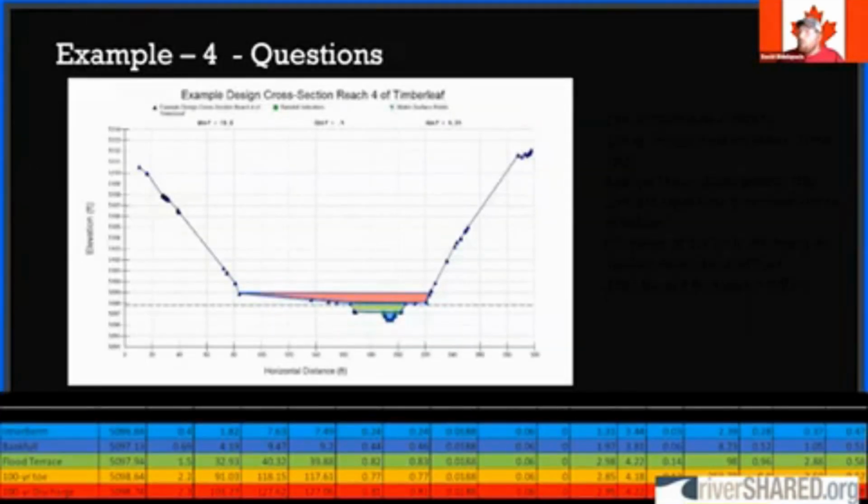So we're moving towards ideas of 4-stage channel designs, multiple channel designs. So we design for a bankfull channel, we design for a floodplain, we design for an inner berm channel, we design for a flood terrace. And these are all important when we're having frequent flooding, to make sure that we're designing to a shear force that's appropriate for the vegetation that could be established in the expected time frame that these surfaces will be accessed. So that's kind of the way that I look at it.